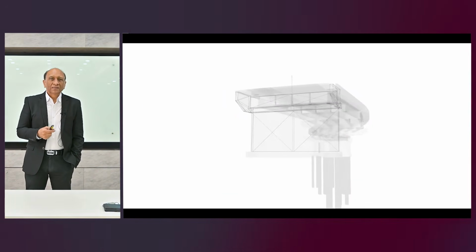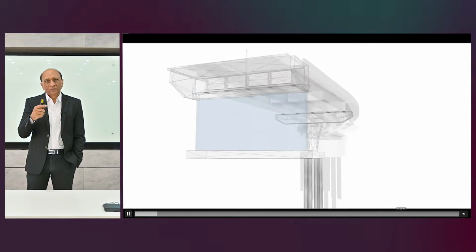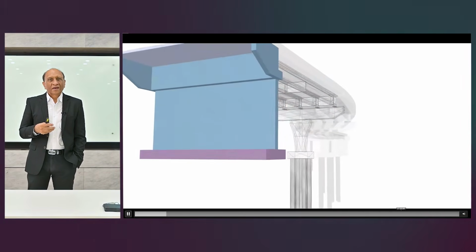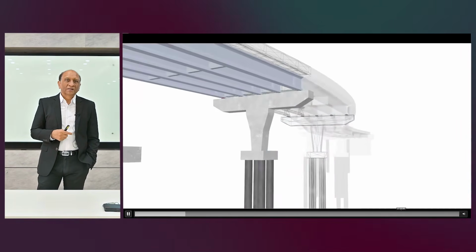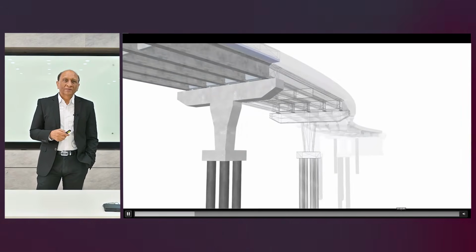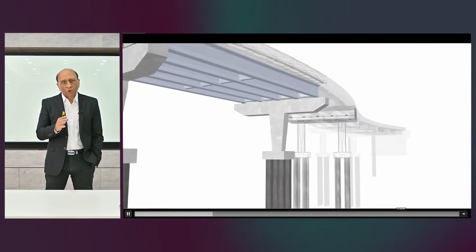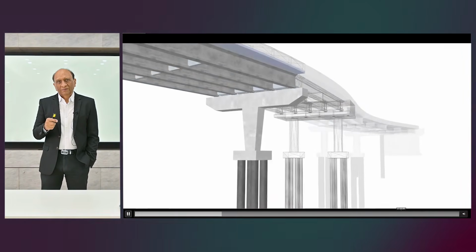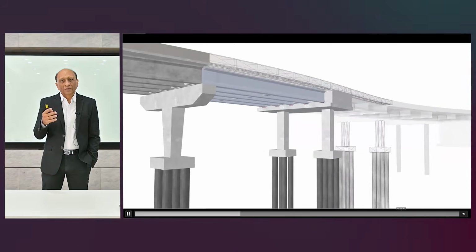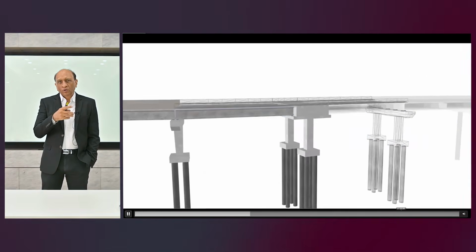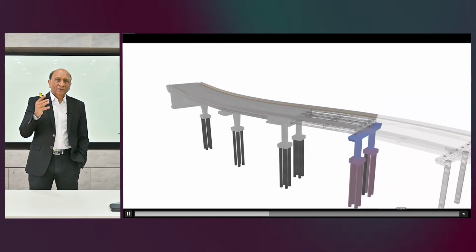So let me show you what a full bridge model made from components can look like. We're just building up, and I'll show you various types of components within a single bridge. So this is the closed abutment wall. That's a single column bent with the sloping. Those are the girders and diaphragm above. We have pile cap. We have another one with the sloping column and the bent cap over there. Then next we have multiple columns with the half joints and a ledge. So you have all these kinds of possibilities of the capping beam substructure as well as the deck arrangement.